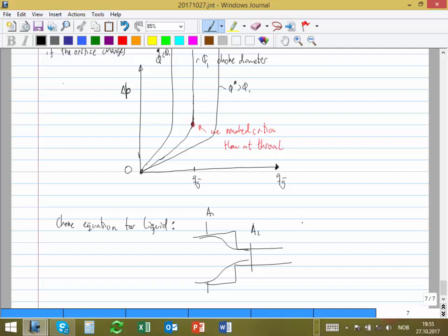So here, if you remember, what was the Bernoulli equation? It was dp over rho, plus 1 over 2 u squared, that's the momentum term, plus g dz, equal to 0. I'm assuming that in this very short distance you have no frictional losses. That's an assumption: the distance is short, so no friction losses. And also I'm going to say the elevation is not an issue. It might be inclined a bit, some millimeters, but really it's not an issue, so I'm going to get rid of that term too.